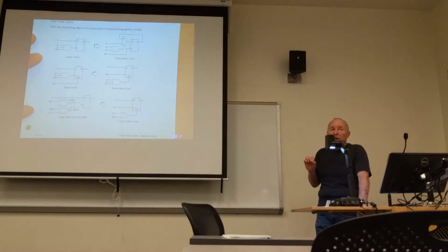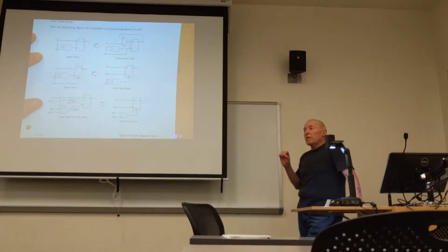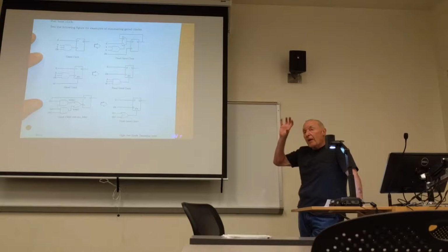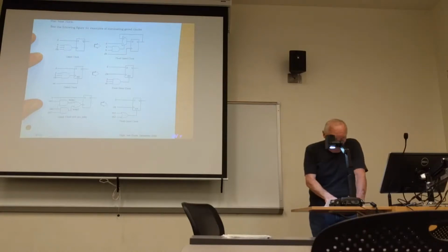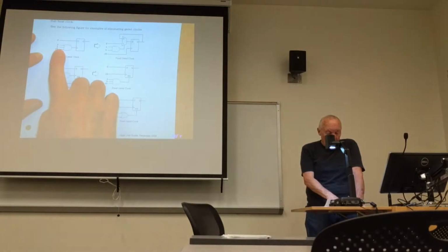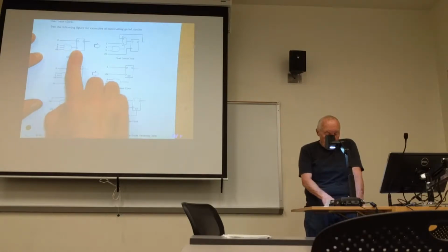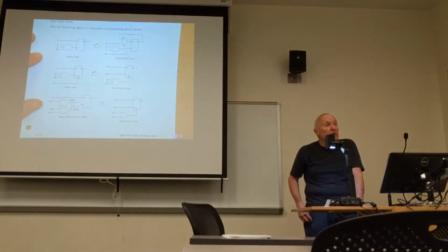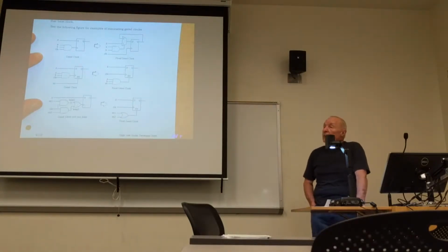In a previous video that we looked at, and we had talked about this on managing complexity, they talked about having a very distinct data path and control path in your design. When you do this, you have moved your clock enable signals from the control path into the data path, and that leads to a more efficient design.